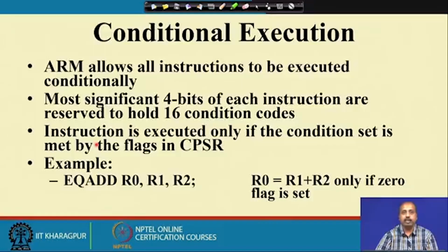This conditional execution is helpful if we have a number of instructions and a number of condition checks. We have seen that it can be utilized to reduce unnecessary jumping in the program, so that conditional execution leads to straight-line code, which helps in the pipelined execution of programs.